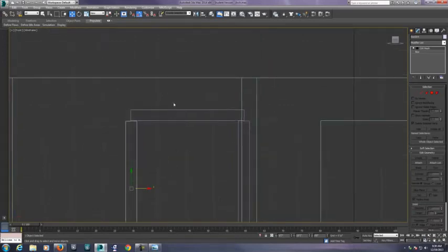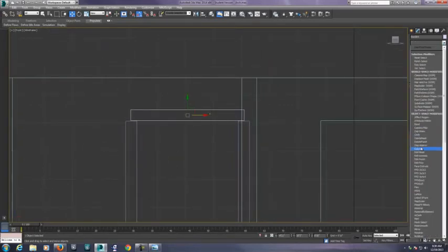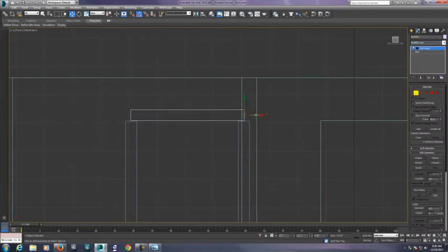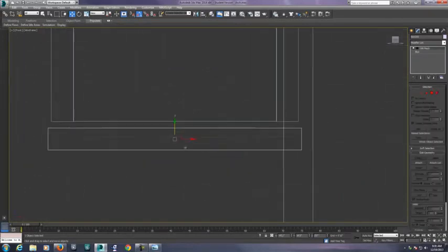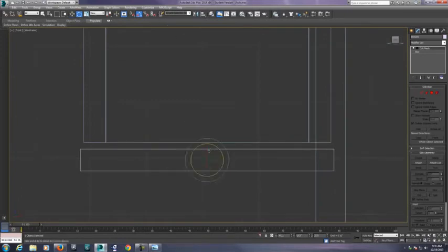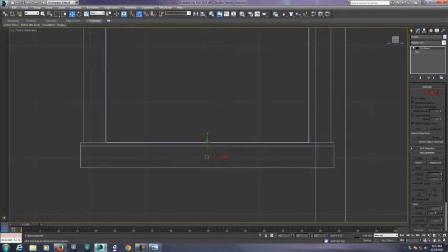Alright, so this is just like a block casing here that's going to allow me to keep it kind of simple. I'm going to show you another direction as well that might help you out. Some of the casing is kind of a perfect box where some of it sticks out just a little bit, maybe something like that, if you see how I'm doing that. Then of course I'm going to go ahead and duplicate that one down here, and I'm going to leave a little gap, and the reason why is that I'm going to create a window sill. I'm going to hold Shift and rotate this up on its side, and I'm going to place that right inside there to create the illusion of a window sill.